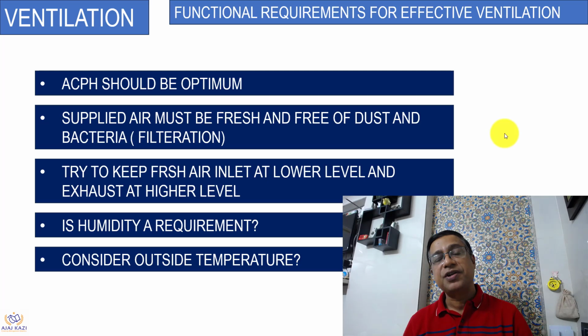Supplied air must be fresh, free from dust. So you need to add filtration. And if the area is very, very sensitive, you need to look at what kind of filtration. When you work in refineries where the outside air is polluted, you may have to go for a carbon filter so that you get the right pressure inside. Try to keep pressure at the inlet at the lower end and the exhaust at the higher end. It's a very simple thing.